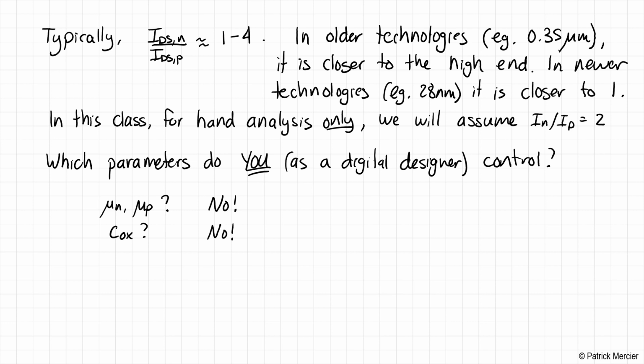Now, there is a caveat to this. Maybe I'll put a little asterisk here, in the sense that as a circuit designer, we are typically given a couple different transistor flavors. For example, in a lot of design kits, we have our core transistors. These are the low voltage, 1 volt, say, transistors. They're designed to operate fast and for digital logic, RF, and so on. These are our main transistors.